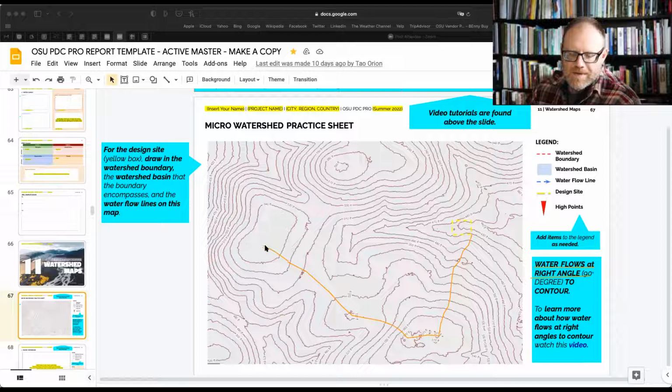Now I'm going up to the top in the middle here because, basically, the top of whatever this mound form is doesn't break the 10-foot line. So we don't know what's above here, but generally looking at the shape, we can think that this shape is going to come up to 2 points or 2 knuckles. So I'm going to cut the difference there. And again, come over here, right angle to contour, right angle to contour, and coming up. And I'm going to come back down here, and again go right angle to contour, and the reason for that is water flows at right angle to contour. Once we get to this top line here, this is basically a ridge and it's going to divide itself, so we can basically cross that line. So this would be the watershed boundary.